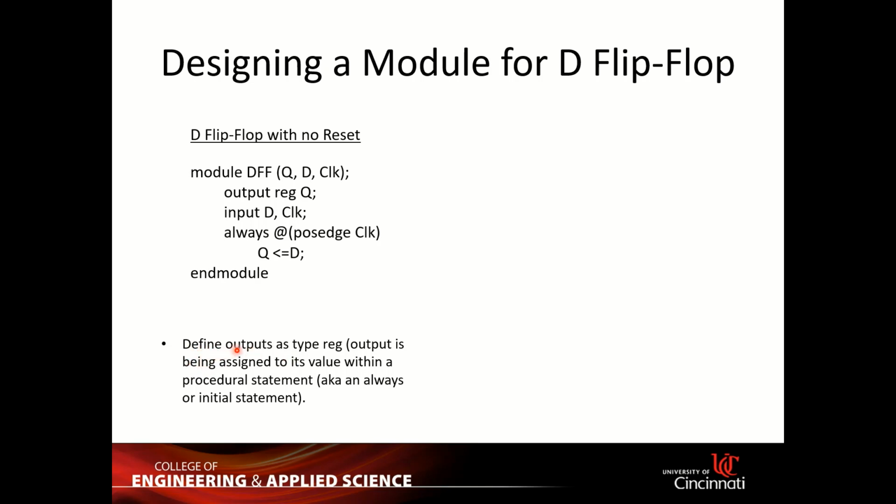So we define the output as type reg. The output is being assigned its value within a procedural statement. Every time you use that always statement, or every time you use behavioral modeling, just a reminder, you need to use this reg type.